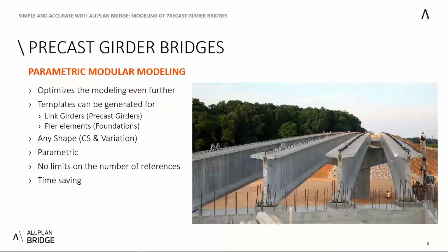A further characteristic aspect that is common for prefabricated girder bridges is the repetition of the shape and length of the girder. Depending on the global bridge constraints, like for example radius of the axis, identical girders are positioned either in the same span or at the same position span-wise. Here, there are no limits, and despite the fact that often for girders standardized shapes are used repeatedly, each bridge is still unique. The new modeling approach is open and therefore supports also this aspect. And to support also the repetition of the girder geometry, we are introducing modular modeling.